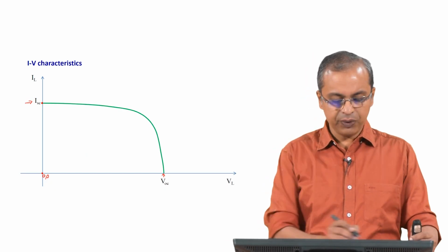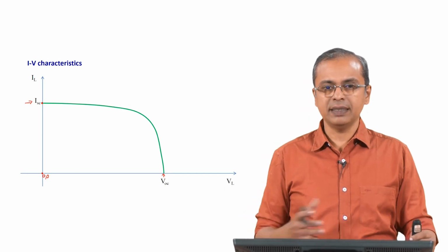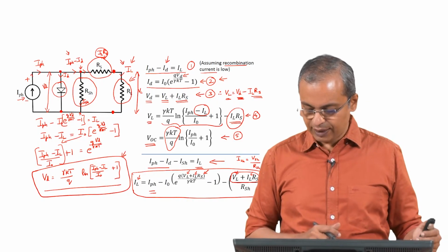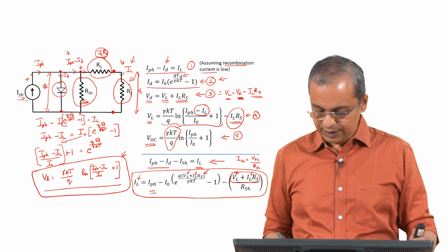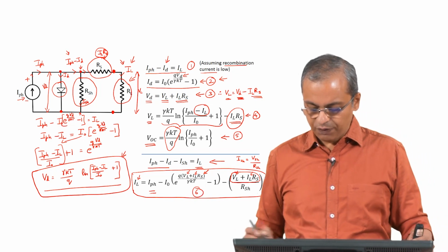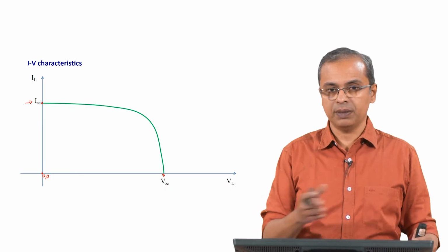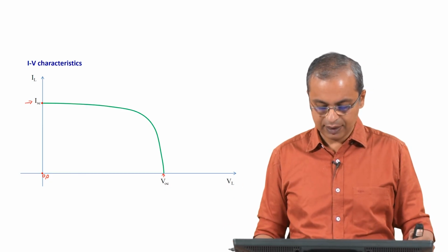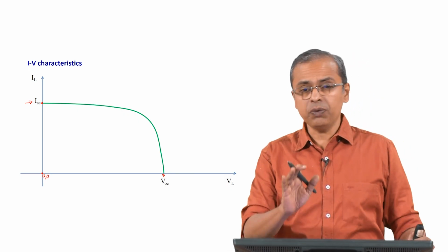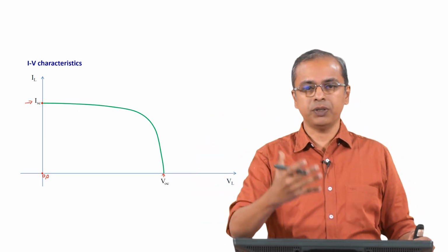You can see that this curve is not linear in any sense, but it corresponds to that last equation that we had down here. Let me call this equation 6. So, a plot of equation 6 is what you are seeing here, which could also be obtained experimentally. You simply have to put it together and measure all these things, and there are some experiments which do that. So, please remember, this is what the external circuit can see from the solar cell.